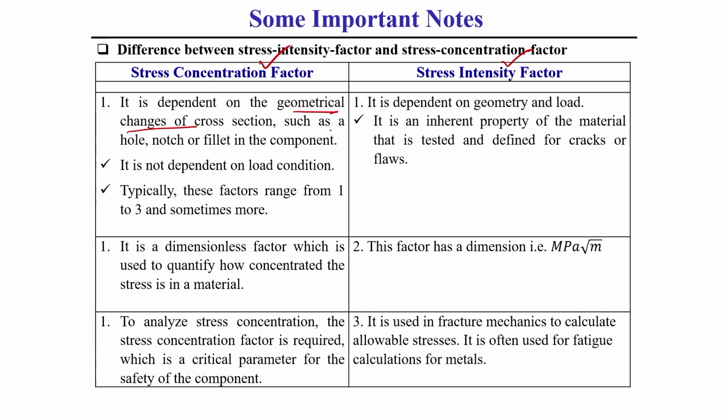This occurs where there are holes, notches or fillets in a component. One thing you should keep in mind: stress concentration factor generally does not depend on load condition, whereas stress intensity factor depends on both geometry as well as load. This you should keep in mind.